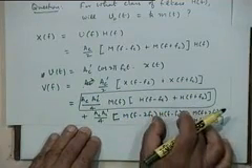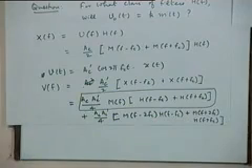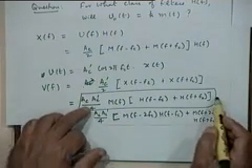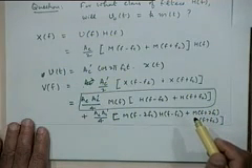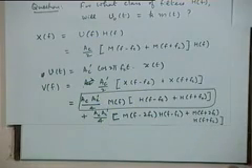H of f was centered around fc and you are shifting it further to the right by fc, so it gets centered around 2fc, right? So this is centered around 2fc, this is also centered around 2fc, and everything is centered around 2fc, whereas this part everything is centered around 0. Okay, if it is all right, then I can proceed further.